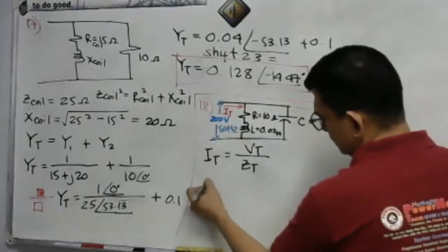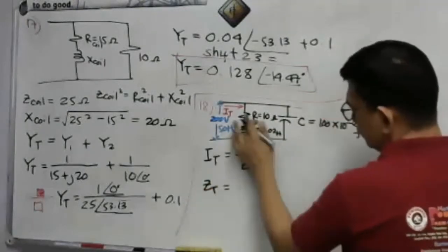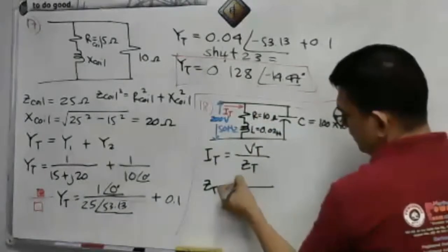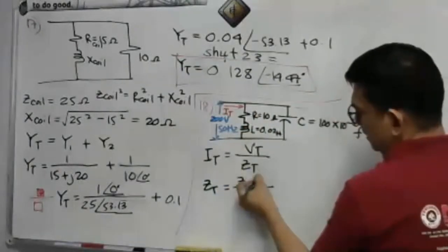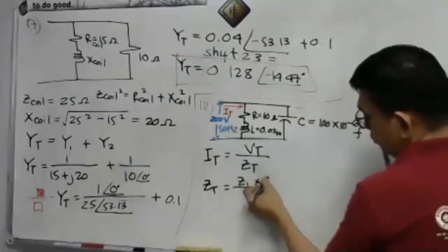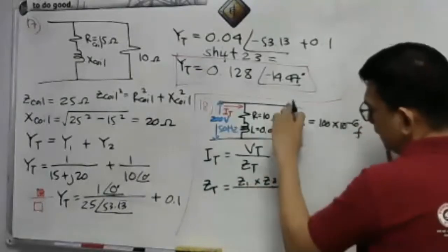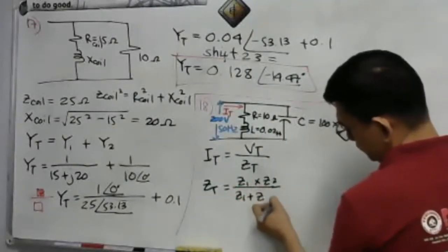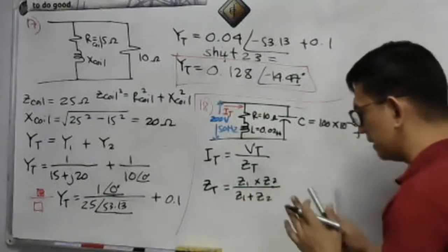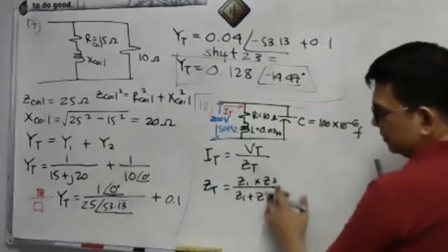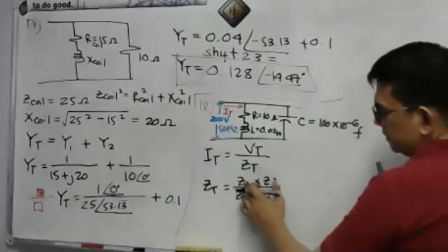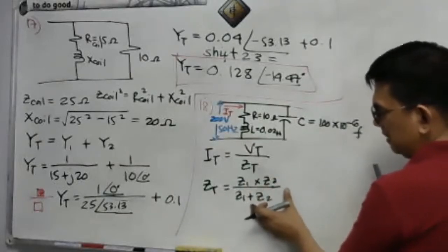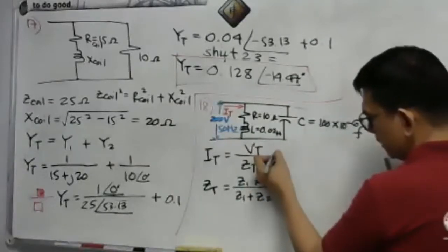The total impedance, remember, this is a two-branch. We may say that the first branch is Z sub 1. The impedance of this coil is Z1. The second branch is Z2, so Z1 times Z2 over Z1 plus Z2. It's quite complicated, this one. Although this is right, this is a correct way. One of the correct ways, I mean. But we can have also this.